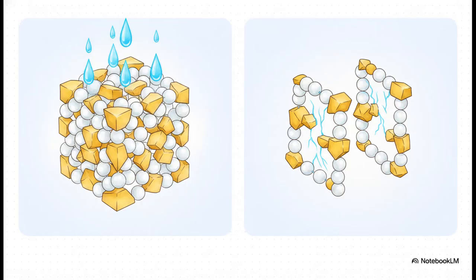Now, the operational mechanics change drastically based on the grain's inherent physical properties. Hard wheat demands extreme conditioning precision, simply because its internal starch-protein cohesion is fundamentally different from soft wheat. In hard wheats, the protein matrix adheres with immense structural tightness directly to the starch granules. This high-tension bond is what defines the kernel's hardness, and it dictates the heavy vector forces required to break it. Soft wheats, on the other hand, have loose cohesion, allowing them to fracture easily along cell walls with minimal force.